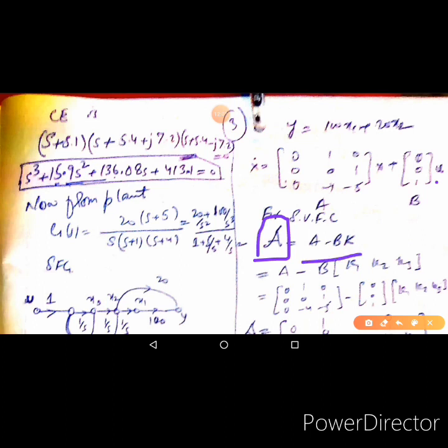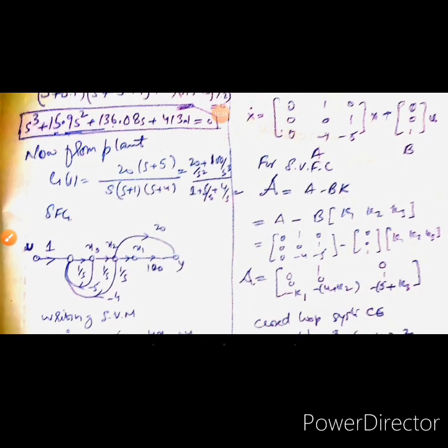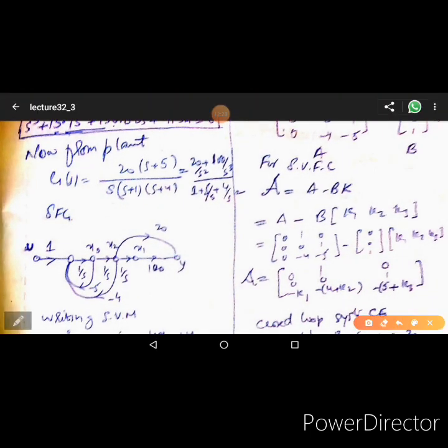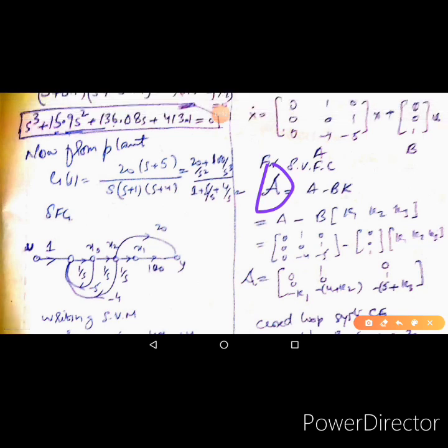When we make the substitution of the control law, which I have told you, using the minus kx, then this becomes the new system matrix of the system with the state variable feedback control, the system that we are trying to make. That system will have this A matrix, A minus bk. K matrix, K is a row vector, and it consists of k1, k2 and k3.